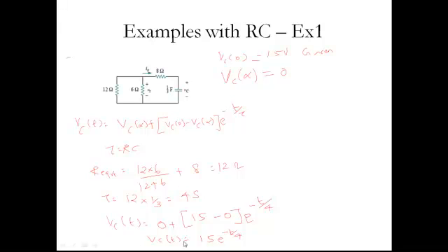Okay, so that is what we have done. By now we know what is Vc of t, so we got this answer. Therefore, now to find I0, you can see the current I0 which is flowing through the 8 ohm resistance, the same current will flow through the capacitance also. So I0 can be written as C into dVc divided by dt.